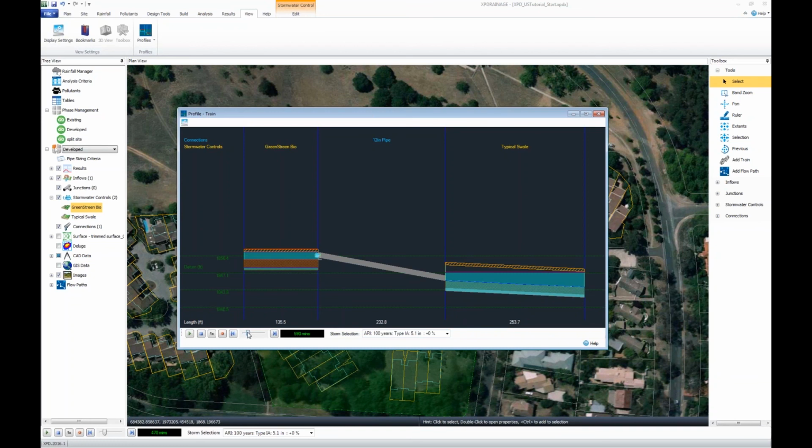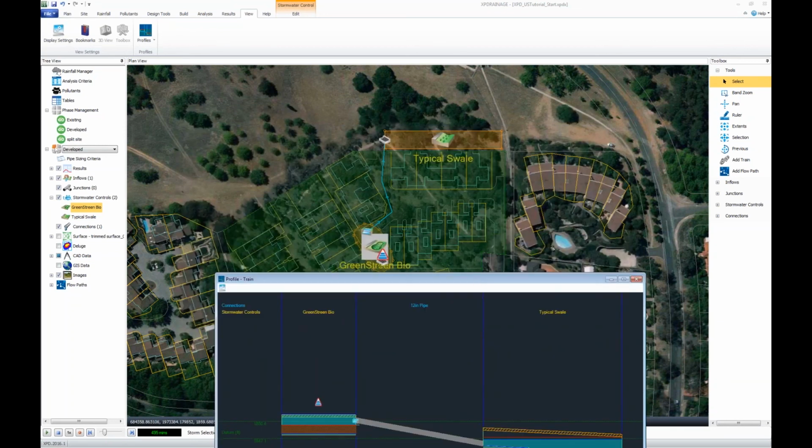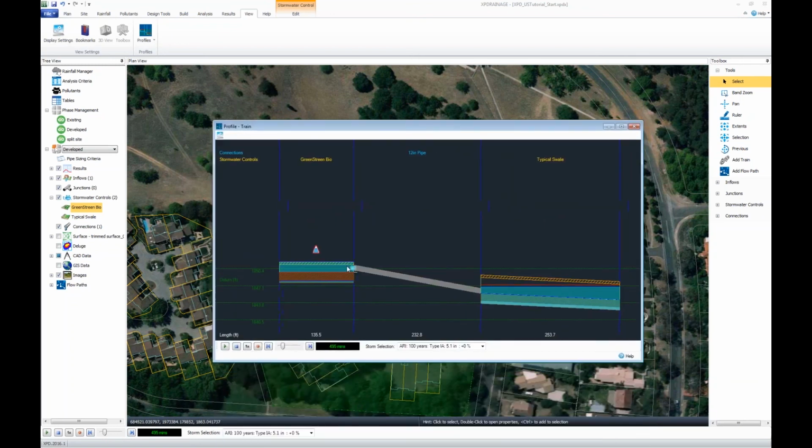So pretty quick to size these facilities where you need them. Clearly for that runoff reduction event, very, very quick and easy. Making it fit on the site in this case was kind of the fun part. And still, maybe I'm still having some flooding concerns at my bioretention system. So in this case, I'm actually still using the kind of lumped site. Well, maybe I need to split up that site. If I could show the results for that, we'd see it be a little different.